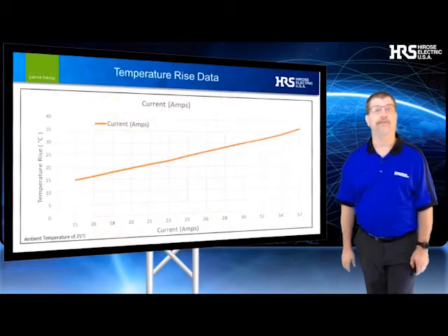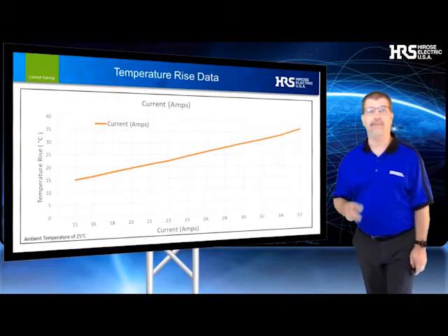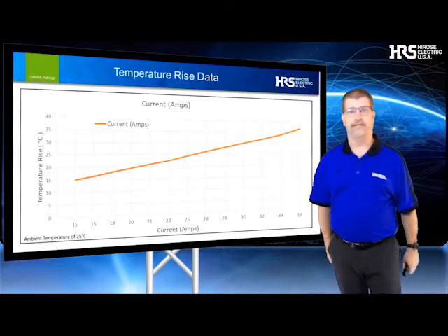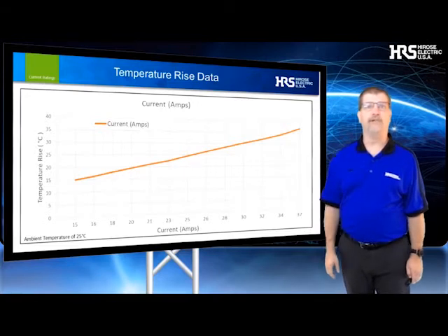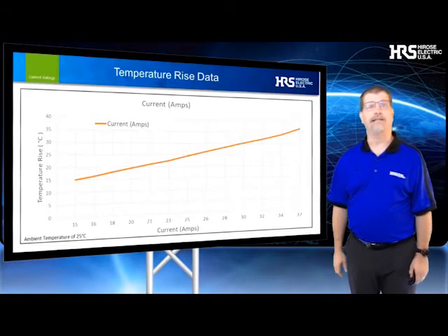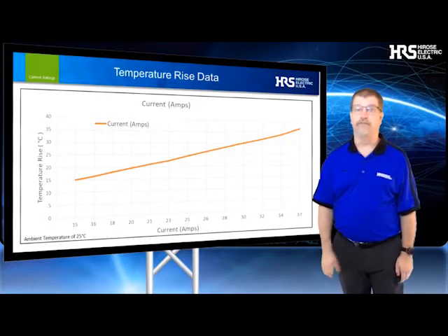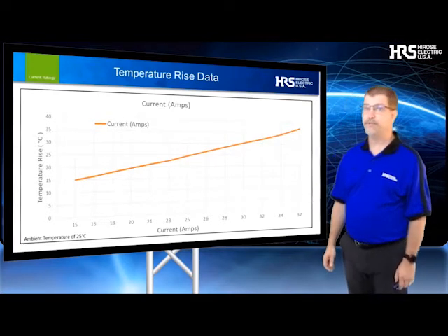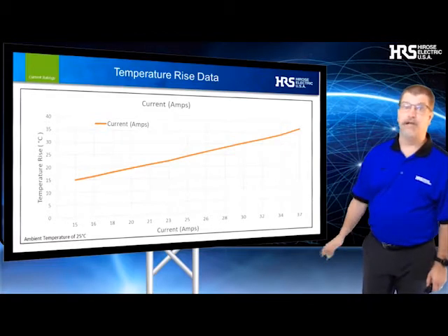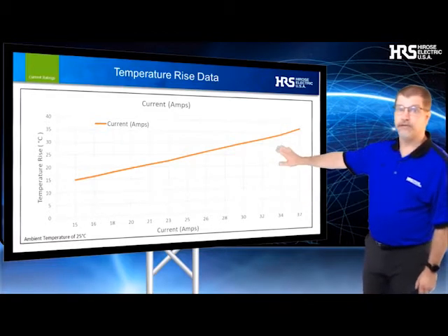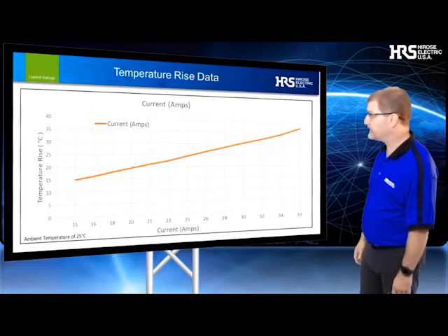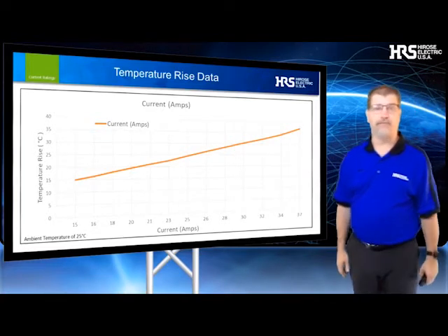Amperage ratings come from the temperature rise of the contacts and the ability of that contact and the connector to dissipate that heat out to the environment. This gets a bit complex because there are a few factors that play into the ratings. First off, most connectors are rated based on a fixed ambient temperature value of 25 C and an expected temperature rise of 30 C. A chart, like this one here that we see, is what you'll typically find with one of these connector ratings when you're looking at the power capabilities.